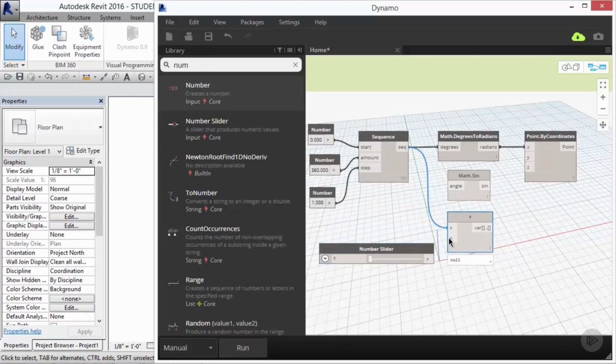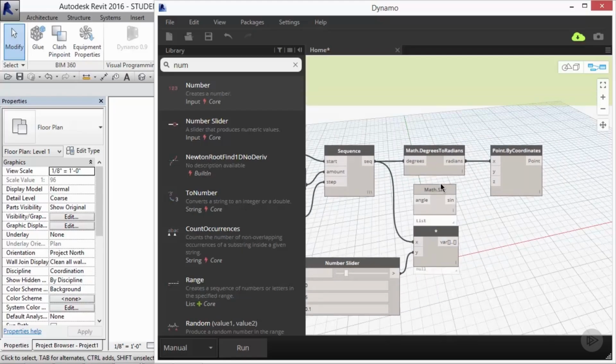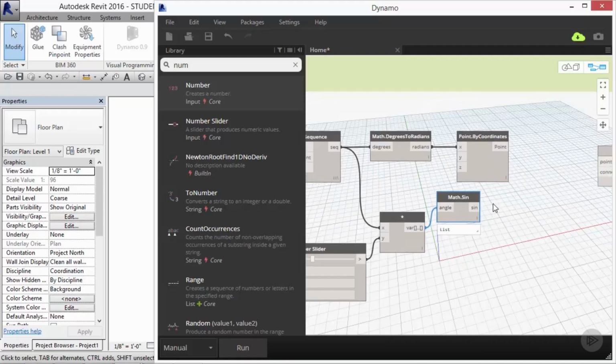If you click the arrow to the left of the number slider, it will expand the settings menu. The settings menu can be modified by simply typing in a new numerical value. The minimum amount that it could possibly be would be 0. The maximum amount for us would be something like 5. And the step is perfectly fine at 0.1. Then we plug our multiplier into the angle.